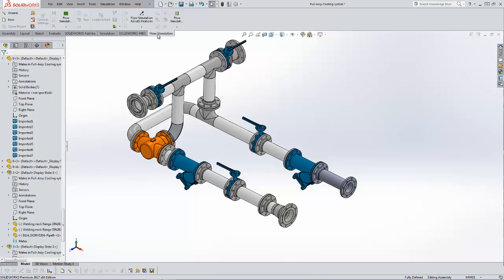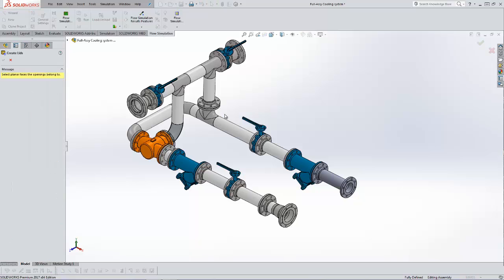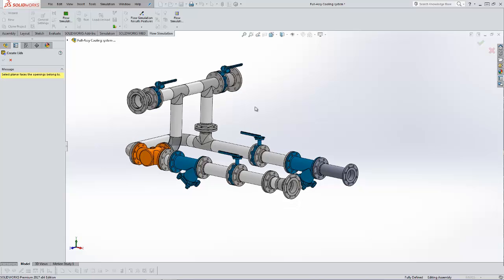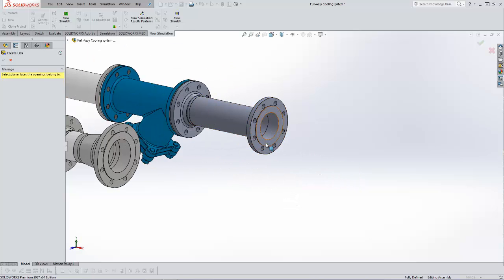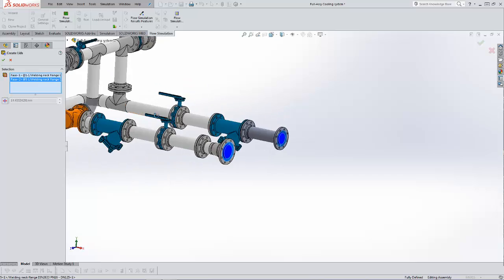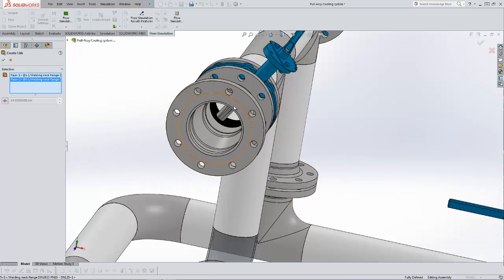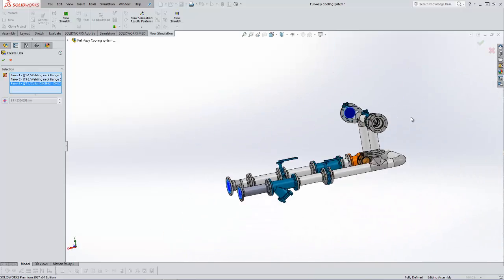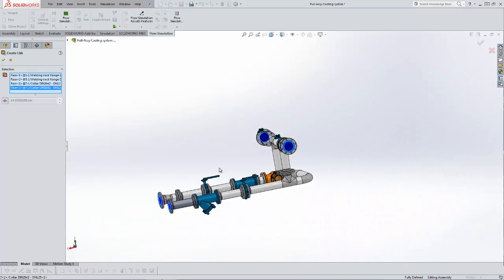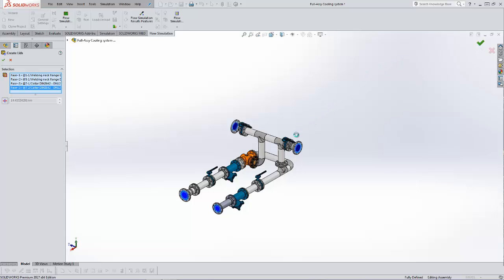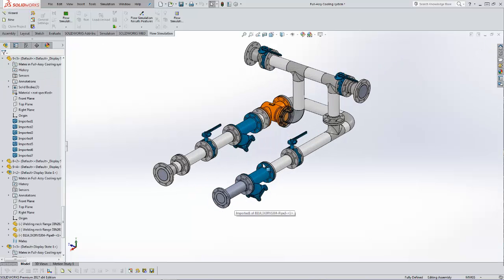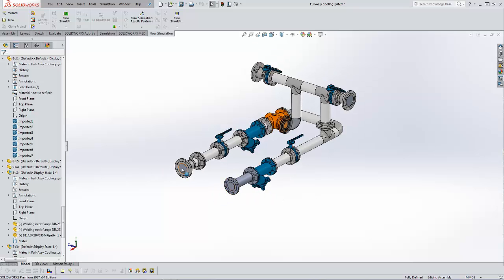We get into the flow simulation. Load the software first, flow simulation, and here create lids. Lids means the enclosures of our systems. So we choose this one, and this one, 3, and the other end will be 4. So it's okay. Now our system is closed. It means the limit or the barrier of our pipeline systems.